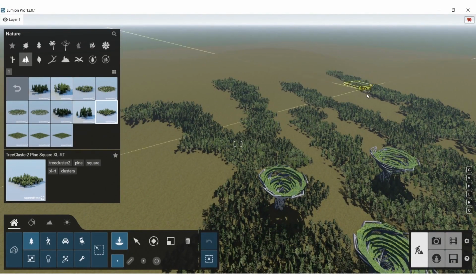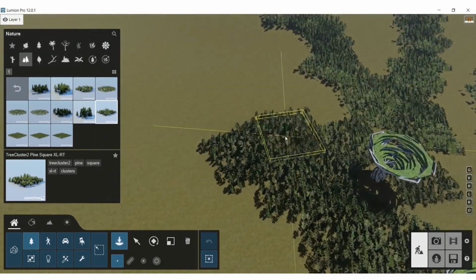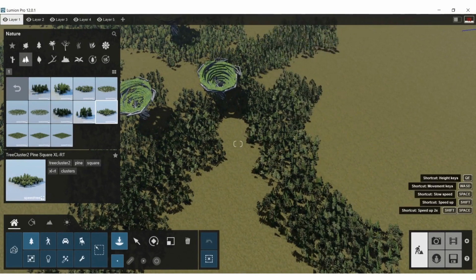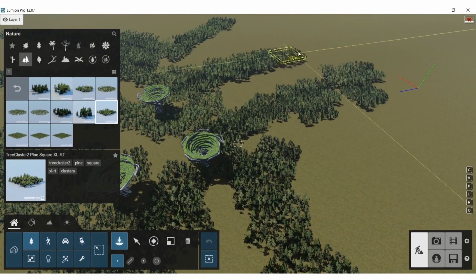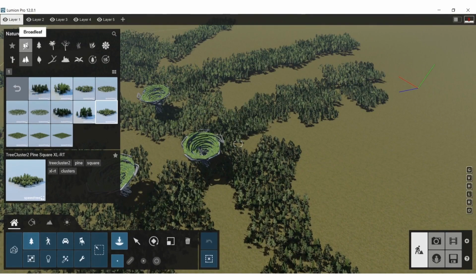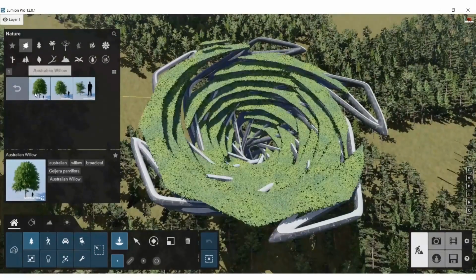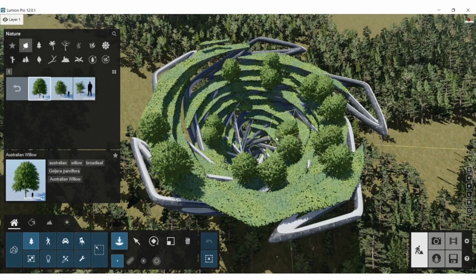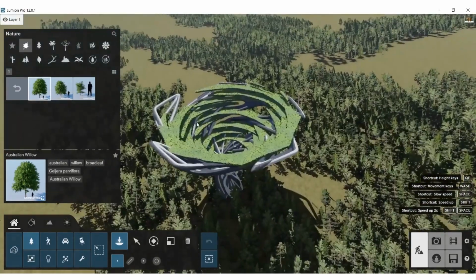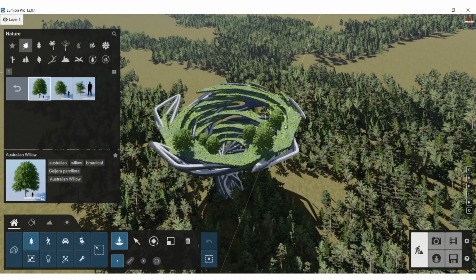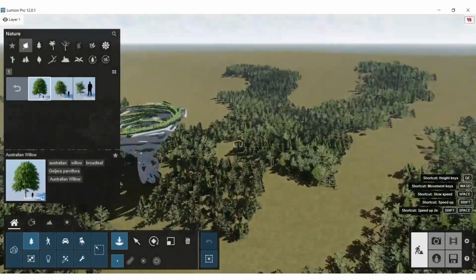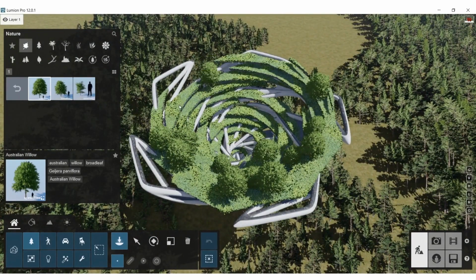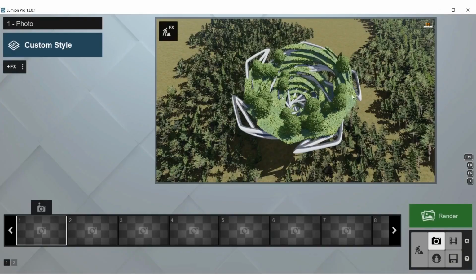But anyway, yeah, we're just adding different clusters throughout the different scene here. Relatively quick. Second, and then I think we're going to start adding actual 3D trees to these structures, just to give it a little bit of variety. And plus the 3D trees in Lumion look much better than the clusters. Clusters are basically just 2D cutouts that are arrayed across from each other, so they give a nice impression for like foreground and background, but not the best for actual 3D shadows and all that. So I'm just sitting here populating a little bit. A little later I add even more trees in.